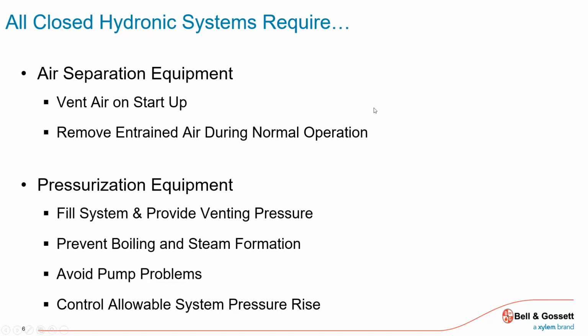Yeah, I was just going to say, years and years ago, before plumbing codes started to change, you didn't have expansion tanks on potable water hot water heaters, right? So you've got street water coming in, doing its thing. You've got showers calling, so you're open to the atmosphere. You're draining, you're replenishing, you're taking the heat out of your storage tanks, your heating vessels, satisfying your load. And then eventually the load maybe shuts off, and now you've got to replenish the tank from what it was. You drained it down, now you've got to replenish it. So you heat that water and it expands, right?